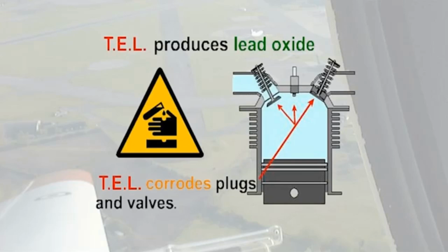To increase the octane rating of a fuel, tetraethyl lead, or TEL, used to be added. For instance, 2 grams of lead were added to each gallon of fuel to take its octane rating to 115/145. The action of tetraethyl lead is to reduce the formation of peroxides, which act as fulminates to explode the end gas, but it has to be used with care, as during combustion lead oxide is formed. Lead oxide is not volatile at these temperatures, and it has a corrosive effect on the exhaust valve, its seat, and the spark plug electrodes.